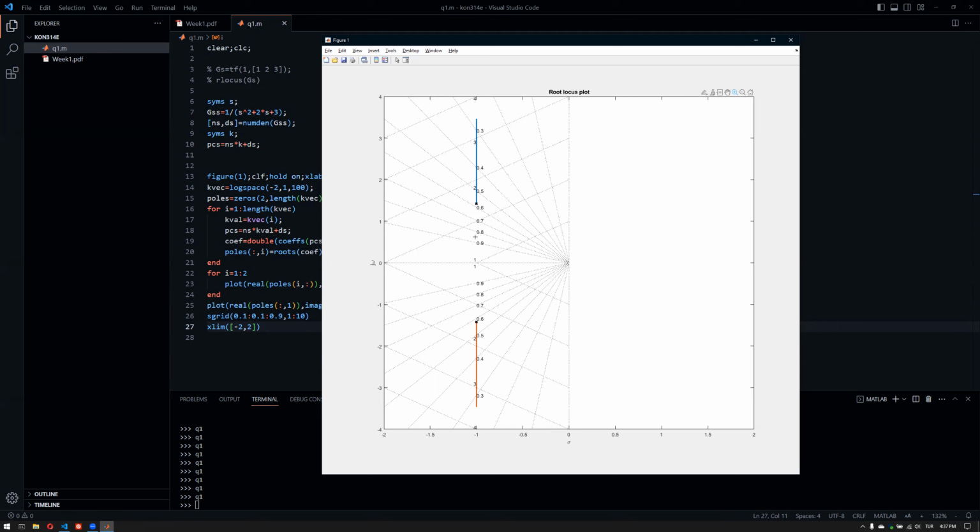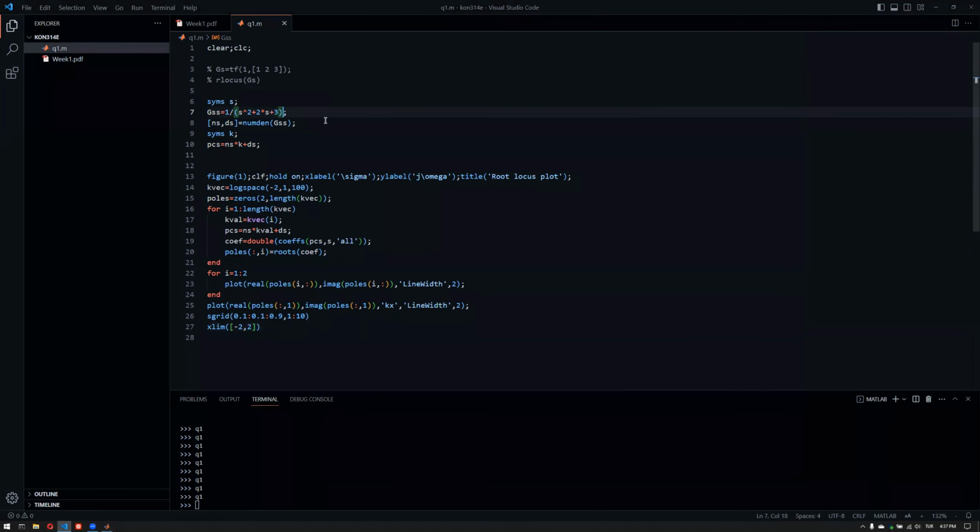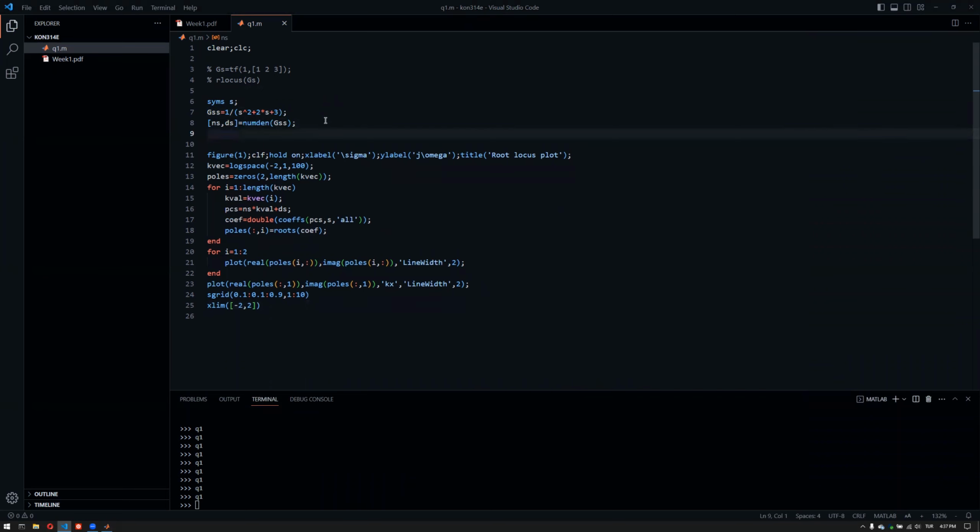Now, it doesn't really change the real part of our pole pairs, and they are all aligned on this line here, so it will not change the settling time. We will use zeta and omega n in our upcoming course weeks for the P-type controller design and for all these time domain specifications, and you will get used to them, hopefully. Now, we might also change the system a little bit. Let me basically get rid of that.